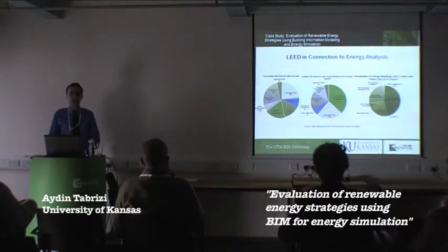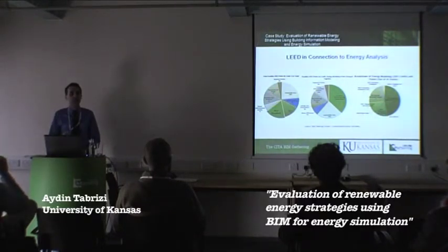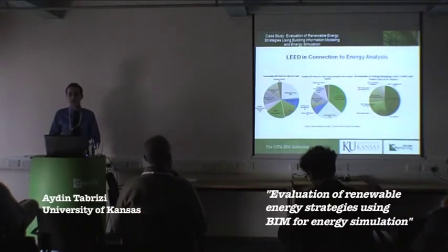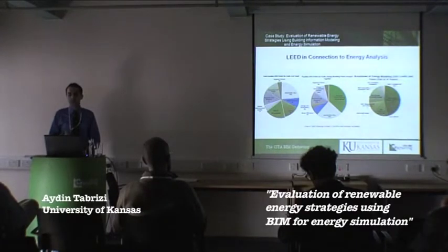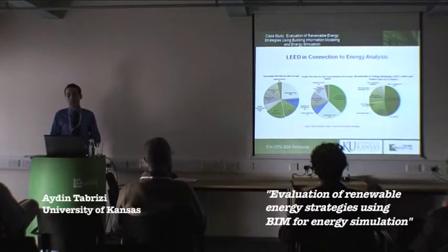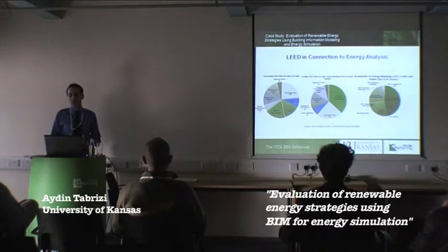And as you see in the second pie chart, if we add up the other energy-related criteria in the other sectors, we can add up the LEED energy-related section to 41 points, which you can see in the right-hand pie chart, where we have 19 points from the energy itself, and then we can add up to 7 points from renewable energy, 3 points from green power, 5 points from measurement and verification, 1 point extra from daylight, and one other point from wastewater treatment.